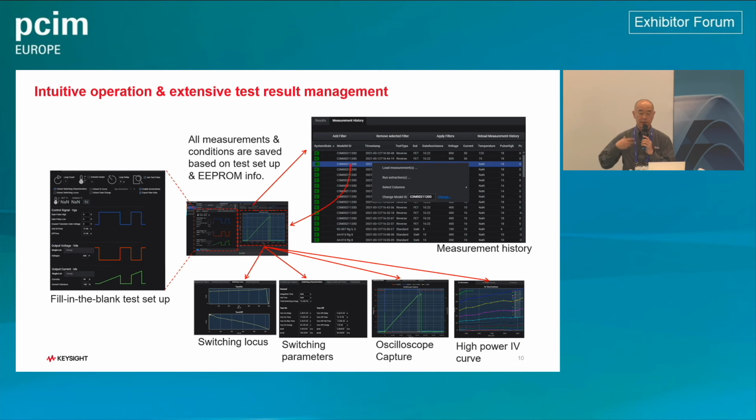So you can just fill in the test conditions like drain voltage, drain current, gate voltage high, gate voltage low. And you can put in multiple values for one condition, like output voltage.